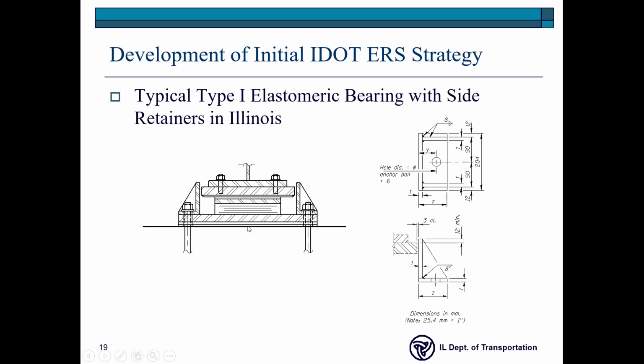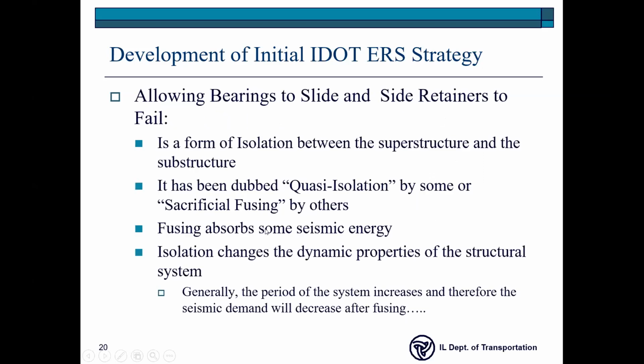Because of that nature, when an earthquake comes and the earth shakes, they tend to isolate some of the earthquake motion between the piers and the deck itself. So not as much of the full design acceleration goes fully into the deck, and that's a very good thing.